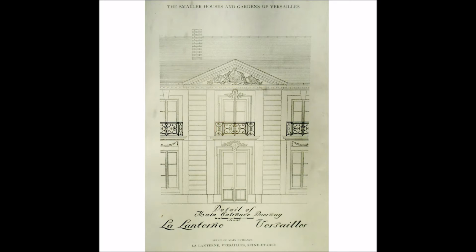If I were designing this for a specific client and a specific location, the first thing I'd do would be to find a local metal worker that can actually produce this kind of a balcony rail. And then I would give them some criteria and request that they provide a design. The criteria would be the building code requirements, the overall dimensions, copies of these photos that we're going to look at, and then how the balcony is going to connect to the house. They will need to know what the finished materials of the wall are and what kind of framing there's going to be for them to anchor into.